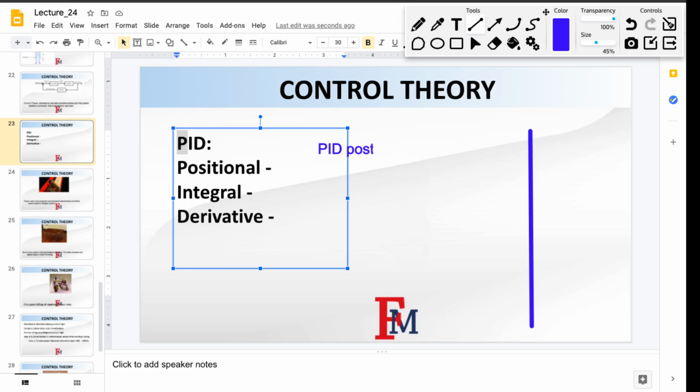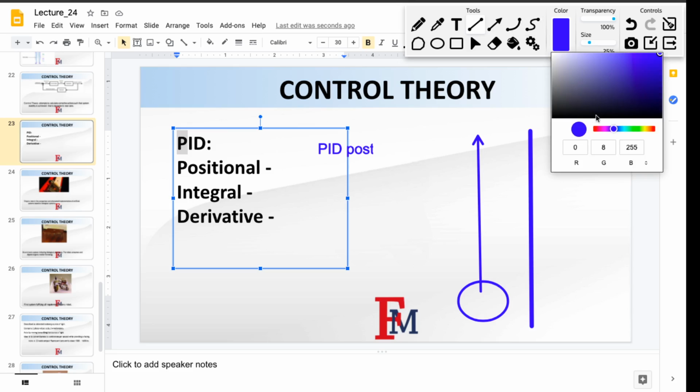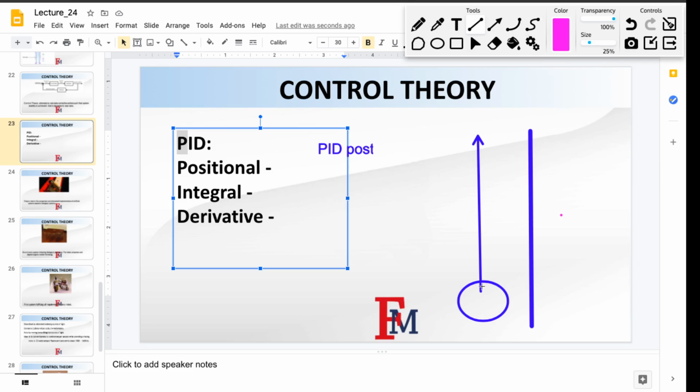So let's say that's a wall, right? And let's say we have a robot. The robot moves over here, and we have the wall sensor. The wall sensor is located over here, and it's trying to sense the environment. When you test that, you'll probably see that the ideal value for that sensor is something like, let's say, 100, right? And let's say you always want that sensor to read 100.